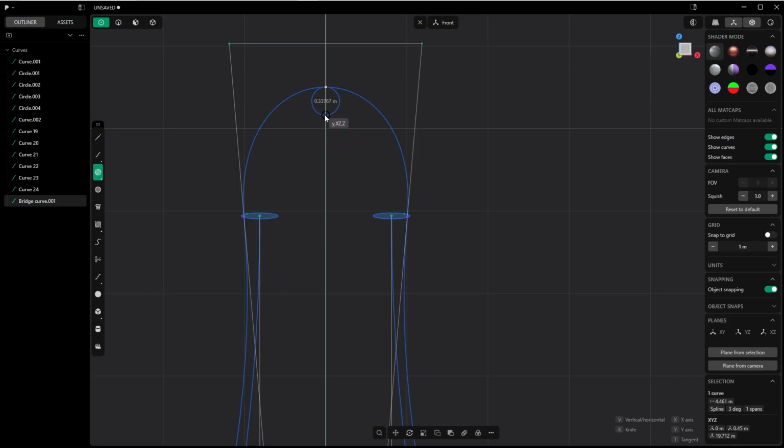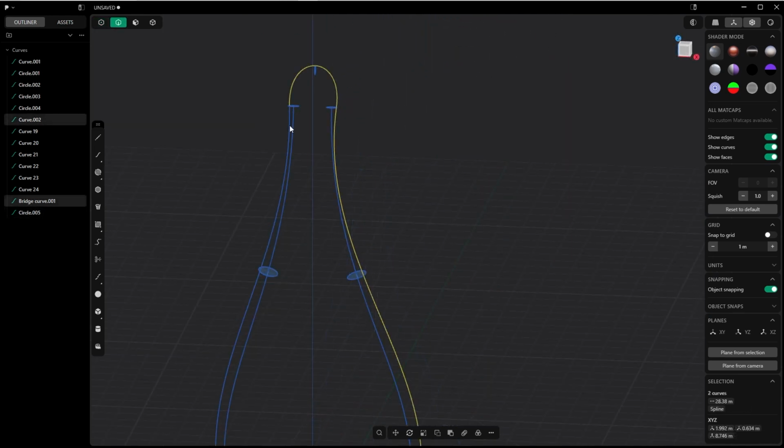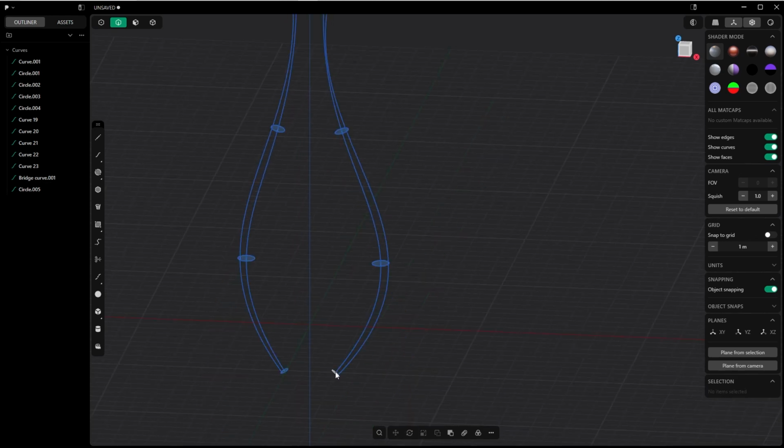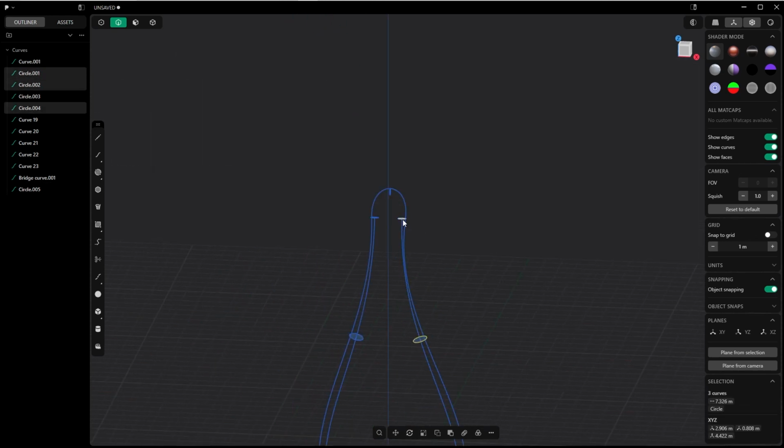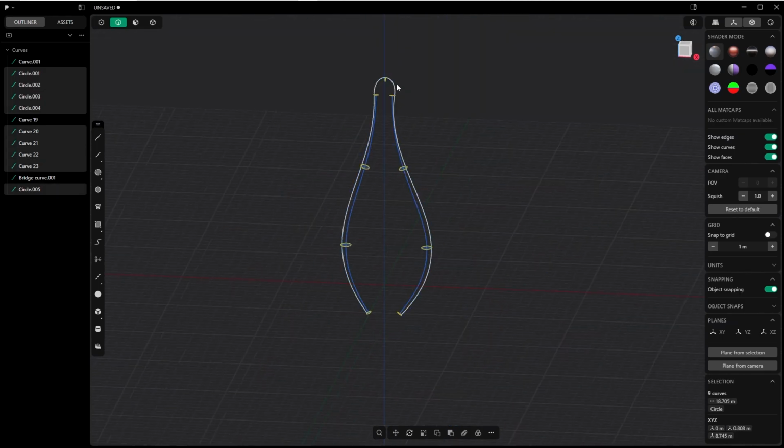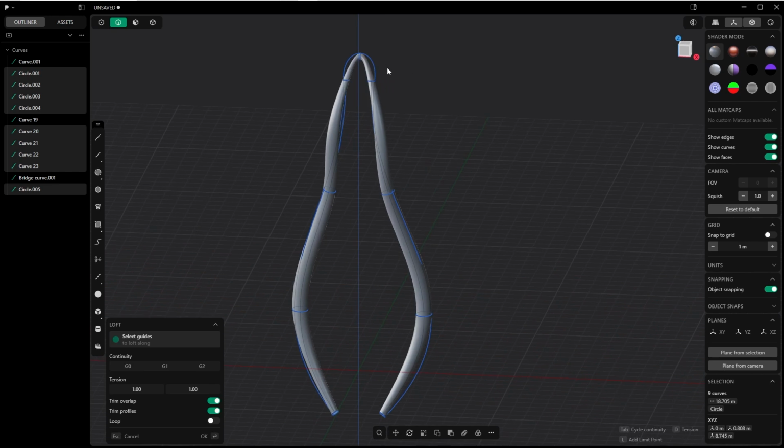And while creating it, press V for changing the direction. Here, this vertical horizontal thing. And okay, select these 3 outer curves, so these 2 outer curves and the one in the middle we have just created, and join them, so we have 1 curve. And now let's repeat the loft with all the circles we have just created. And select them one by one with the correct order, and press L for loft and Shift for selecting the guiding curve. And that's what we have.